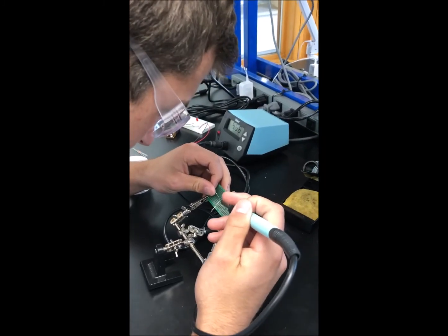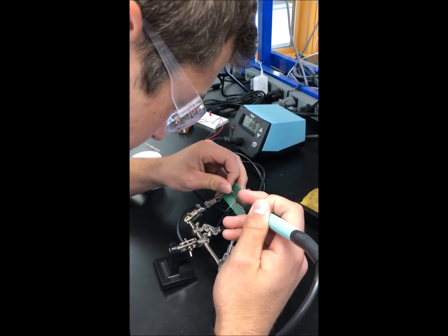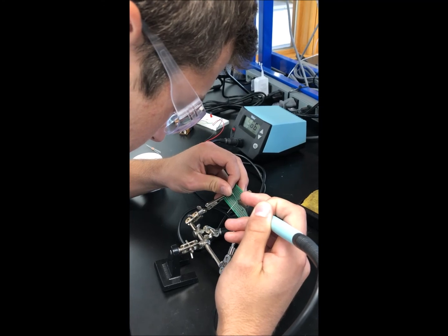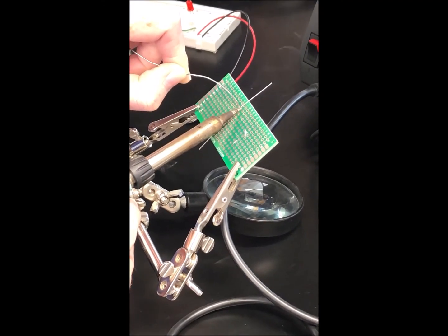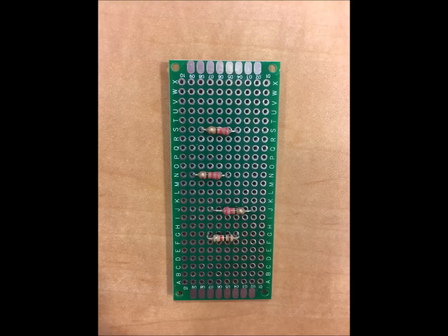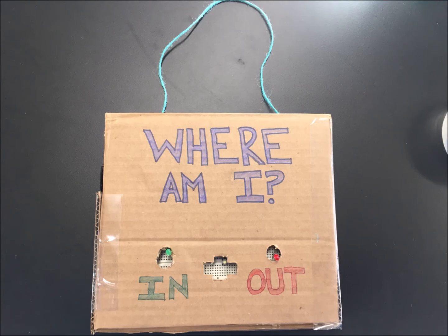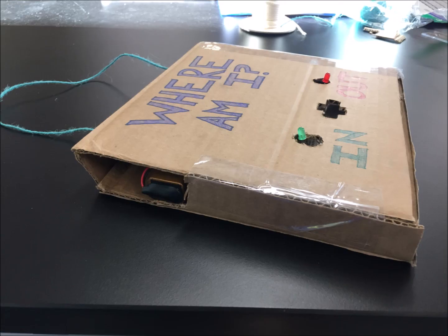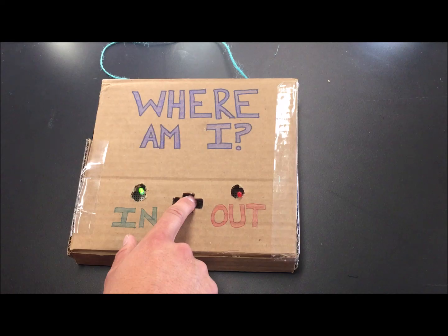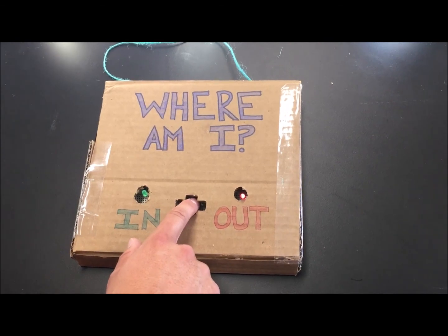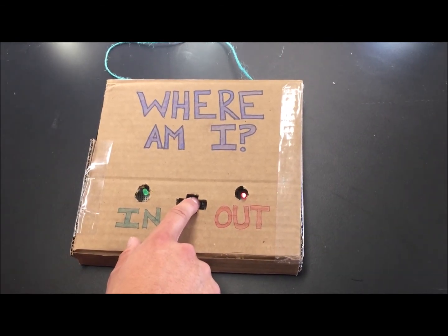In addition to building the circuit and writing the code, we were able to hone our skills of soldering. We learned to be conservative with the soldering iron, since it only takes a few seconds to get a good join between the solder and the wire. Using our new skills, we were able to create a working circuit and dorm room sign, and we feel confident using our new knowledge to aid our team in the upcoming prototyping process.